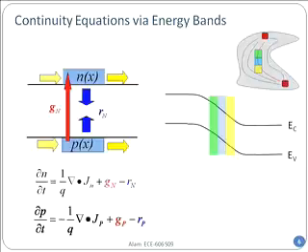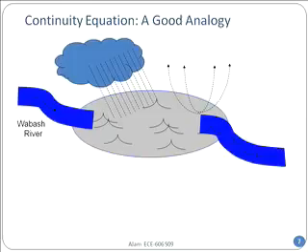Holes have been created, that means electrons have been pumped up, but that does not change the total number of electrons. When something got recombined, an electron in the conduction band came down to the valence band. But if you look at the material as a whole, of course, electron and hole number remains the same, no problem. Individual components can change easily, electron and hole number, but not the global number. It's a very important thing to remember.